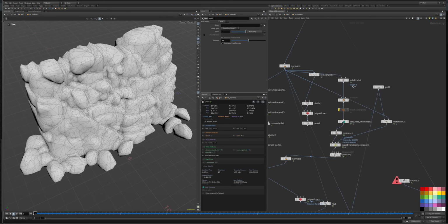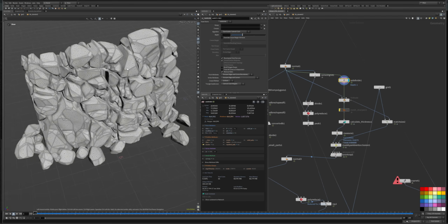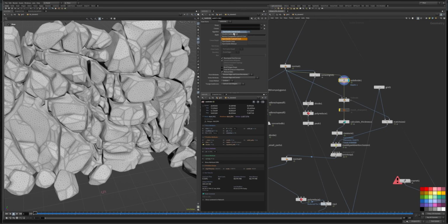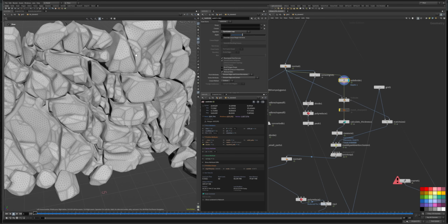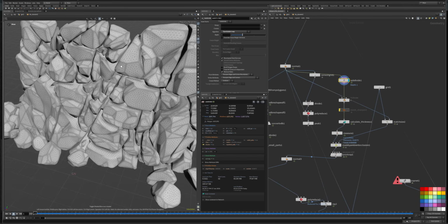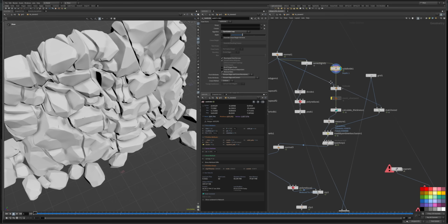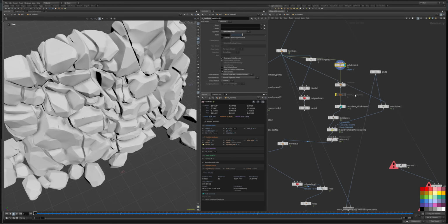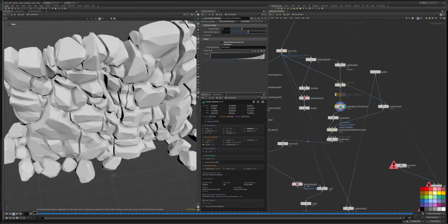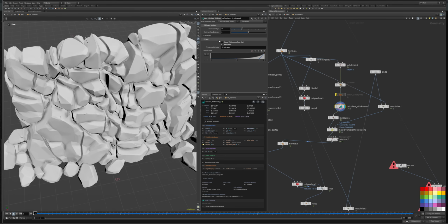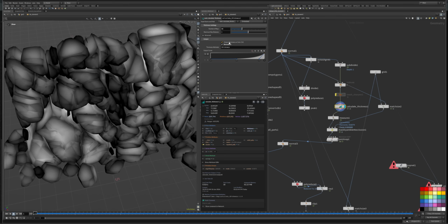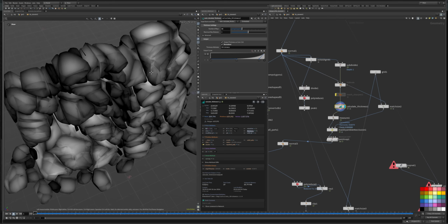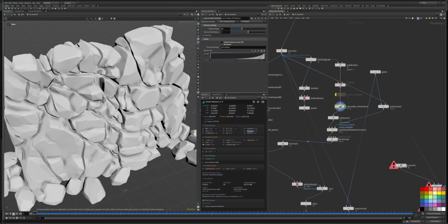And then I get the subdivided model for the high poly, right? I'm actually going to use the loop because I think it's much better to have the triangles over there. And then I get the thickness. The graph is a mess. I was just playing with it too. I get the thickness. So what is the thickness doing here? Basically, we're going to use that for texturing. So this is the reason why I'm getting that.